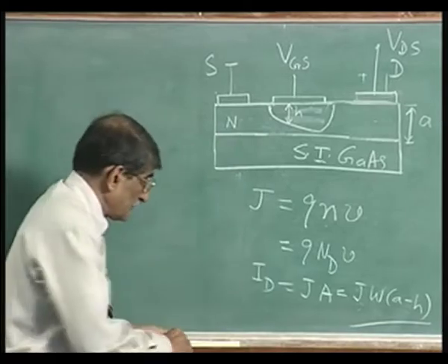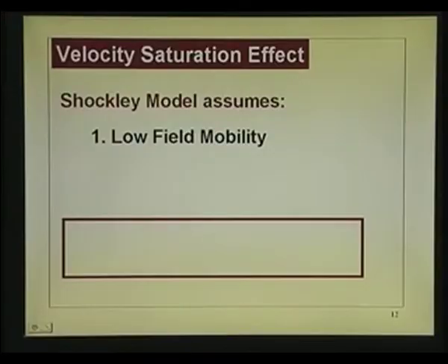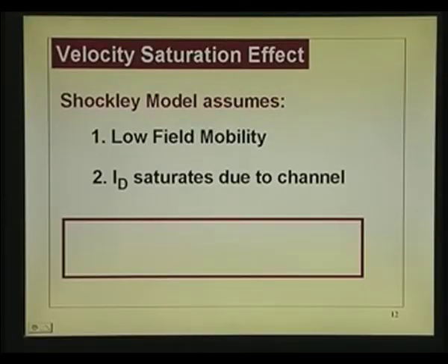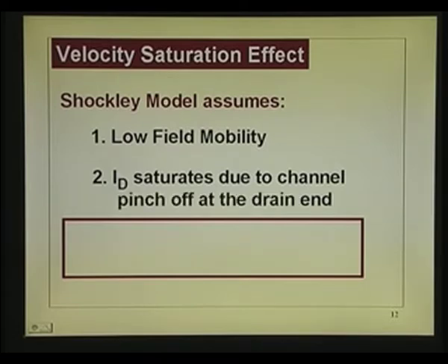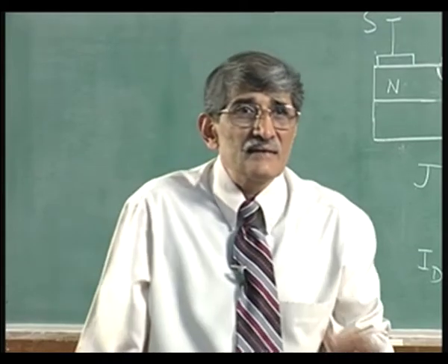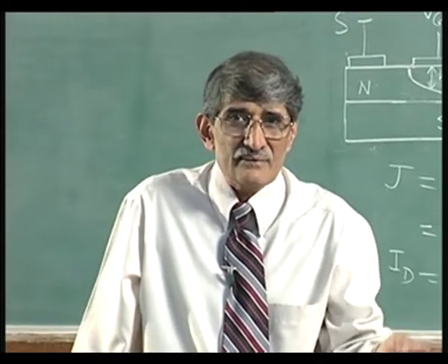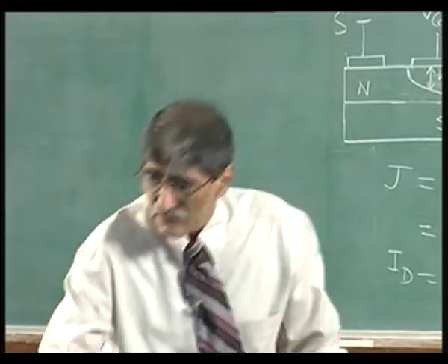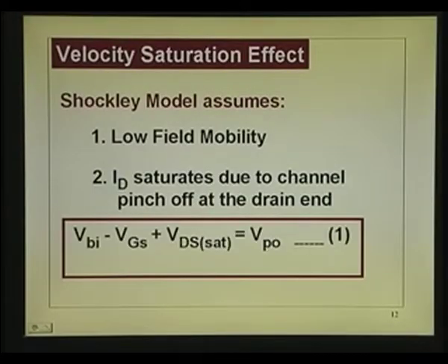Now, to illustrate that, I d saturates due to channel pinch off at the drain end. That is what Shockley said. What we are telling now is the channel need not pinch off. The channel need not pinch off for the current to saturate. That is what we are trying to tell. All that is required is that the velocity should saturate. So that means you cannot use that equation.